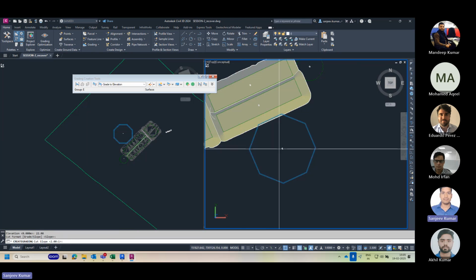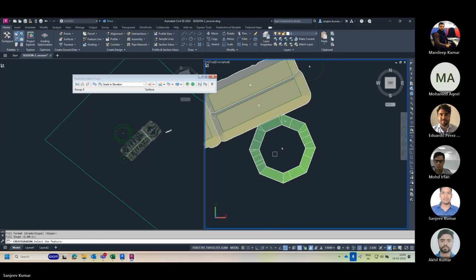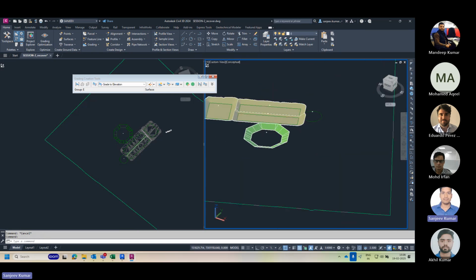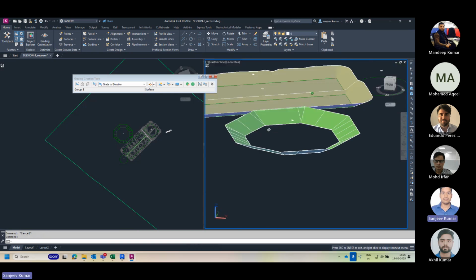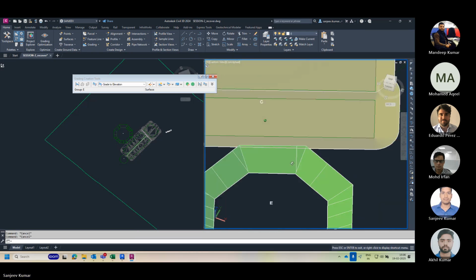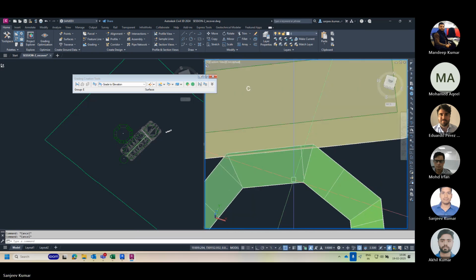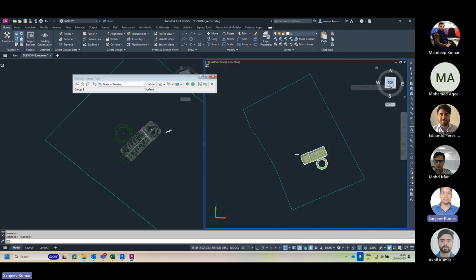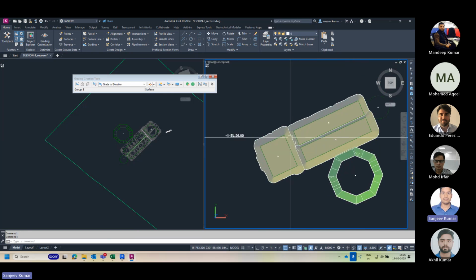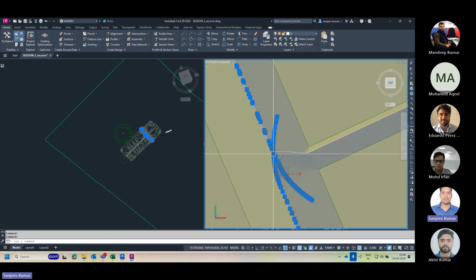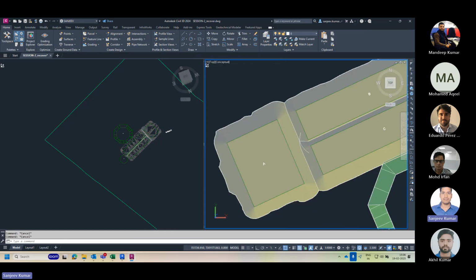Now the cut slope is again 2:1. Fill slope is again 2:1. And we see at that time it has not gone outward, it is now grading inward. So these are some options we can practice. These are the main tools we are using in our excavation model.